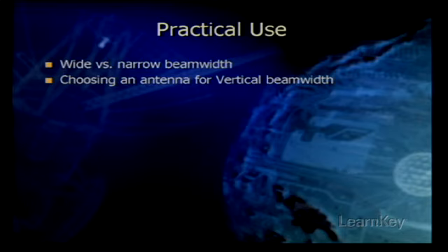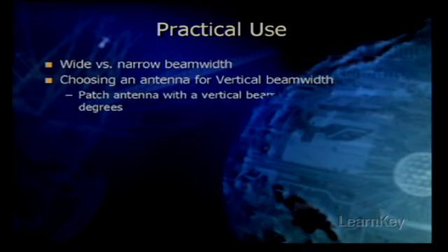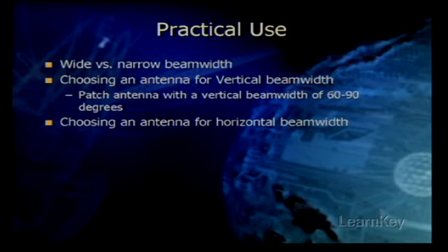For complete coverage on the floors directly above and below this floor, a patch antenna could be chosen with a significantly large vertical beam width, such as 60 to 90 degrees. After some testing and site survey, you find that your selection of a patch antenna with 80 degrees of vertical beam width does the job very well. Now the horizontal beam width needed must be decided upon. Due to the length of the hallway, testing may reveal that a high-gain patch antenna must be used in order to have adequate signal coverage at the opposite end of the same hallway.